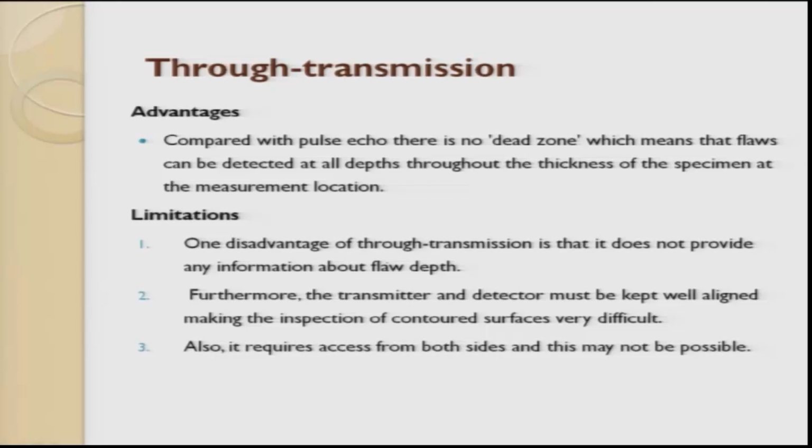So, what is the advantage? Here there is nothing called a dead zone, which was there earlier, and here it is giving much more perfect or reliable signals, and even a small variation in thickness can be quickly figured out by this through transmission.